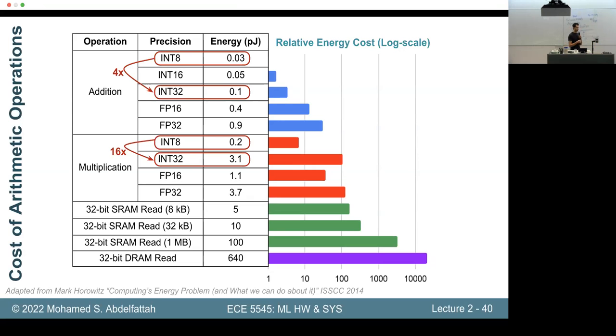And that's why you will see new chips like the TPU support int 8 as a first class citizen, especially for inference. You will also see it in tensor cores and GPUs, where they're also focused on reduced precision. I think now they also have FP16 precision in tensor cores, but the first version only had int 8.